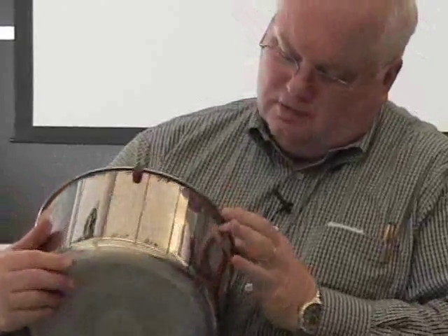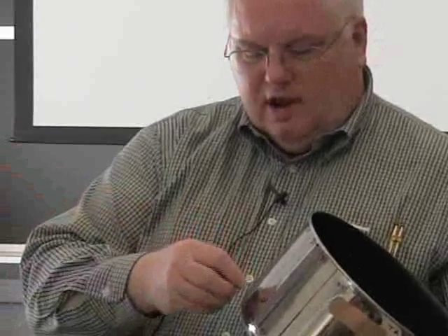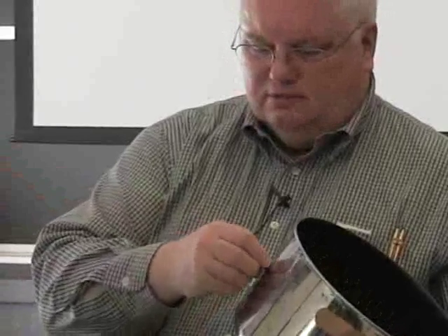If I pass it around, there's a few cracks around here, more than that. Well, there's two here, there's two here, and there's one. Maybe it's only got, no, it's got three right there. Okay, so they asked me, why do we have these cracks? And so I went and got my magnet, and I said, because you've changed the structure of your steel. It's very magnetic up here, and it's not magnetic down here. Right? I'm going to pass that around so everybody can.